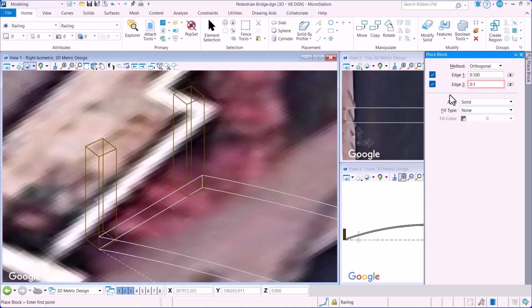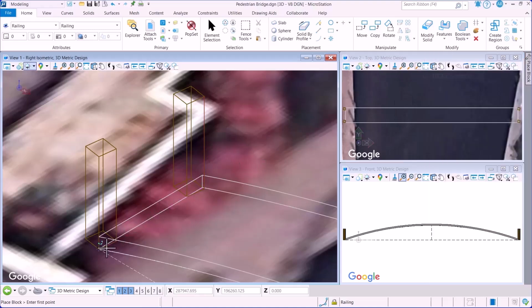Select the front bottom corner of the walkway. Then, with cad-draw active, hit the O key to place the origin at this point. Hit the S key to rotate the plane. Enter 0.1 into the X box and 0.3 into the Y box. Clicking will now place the box in this new location in the center of the post.